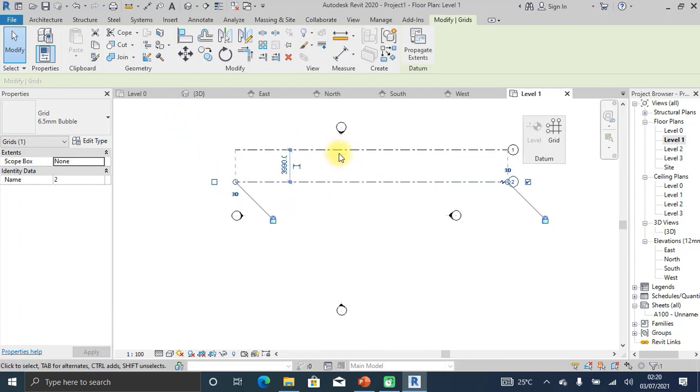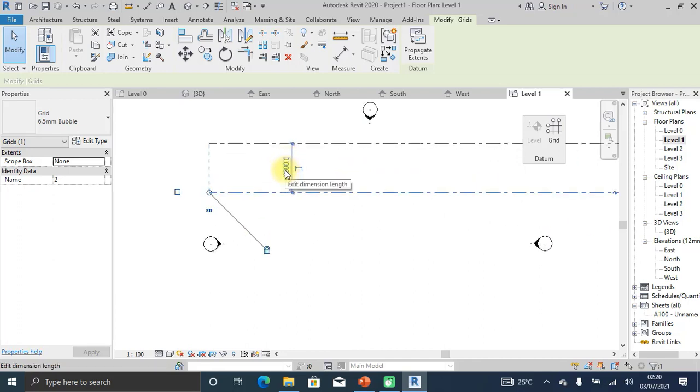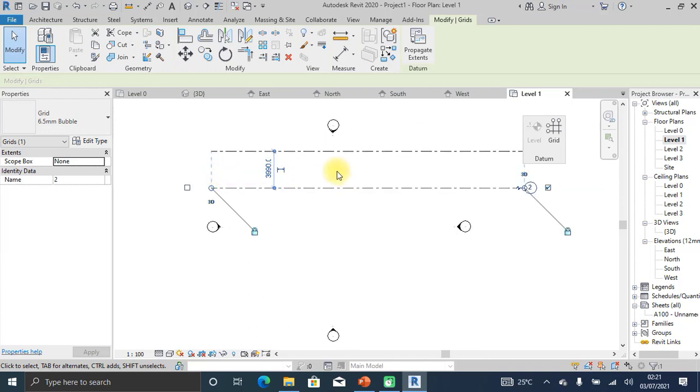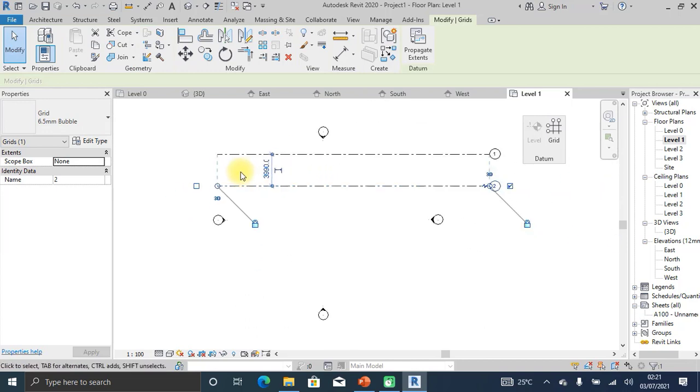So another interesting thing about Revit is that you can work between units. So initially we had set this particular model to be in millimeter as our unit. But now in this particular view here, whilst creating your levels or any other design component or element, you can go ahead and type whatever unit. For instance, let's say I only know that this grid line should be 10 meter away from this other grid line, or let me say 10 feet away from this other grid line.